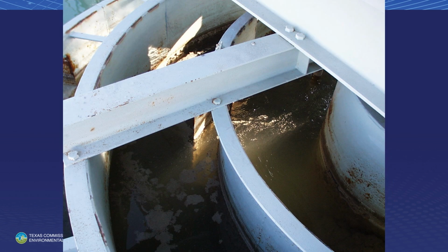This is another issue that I find quite often with solids contact clarifiers, particularly the old ones that have been around long enough so that some kind of contractor has come in and drained them down and cleaned them and painted them for you. It is really pretty important to make sure that these gates that are on the inside of this clarifier are set at the appropriate angle. And I've seen them set everywhere: wide open, just straight out, or angled like this and angled at different angles. But there's a particular critical angle that you put them at. The manufacturer, when they built the thing, put it in that. Do you see what I'm talking about there?